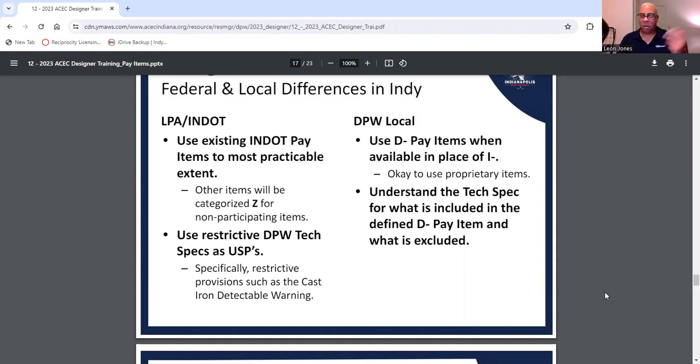Now, we'll talk about materials in a later video, but basically when we talk about detectable warning surfaces, it's this mat, basically 2 by 4 feet, and you see the dome sticking up. It's called a detectable warning surface. Now, what that's for is if you have somebody blind that's getting ready to cross the street, when they're coming down a curb ramp, they can actually feel the domes on their feet that they're getting close to the street.